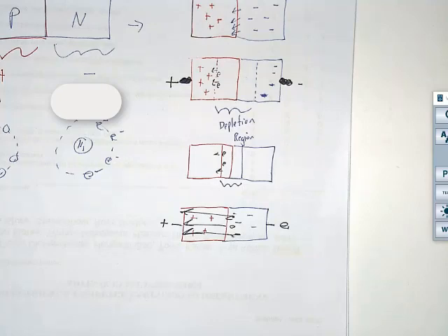Okay? Now, a whole lot of stuff has happened here. This is craziness. We took materials that were an anion and a cation, and we put them together, and a depletion region formed. And we said, if I want to use that thing, I have to apply a voltage to it to get current to go through it. But when I applied that voltage, it didn't start flowing right away. So if I put like 0.1 volts on that thing, what happens is the depletion region shrinks a little bit. And then I put like 0.2 on there, and it shrinks a little bit more, and a little bit more. And I get up to like 0.5, 0.6, 0.7. Current's not flowing, okay? And all of a sudden you get to like, let's say 0.75, and all of a sudden, boom, the depletion region's gone, and all of a sudden electrons start flowing.